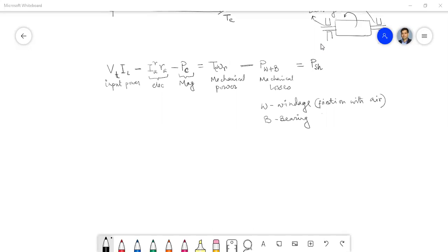Sir, one second, sir. EB equals Z phi. Due to the residual flux in the ferromagnetic substance, the residual flux in turn generates an EA in the armature, and that in turn generates the field current, which again increases the flux, and that way a current flows through the armature, because of which the back EMF is generated, because EB is exactly the same as EA, which is ZP by A into phi N. So for that, the voltage you are giving here is not required.